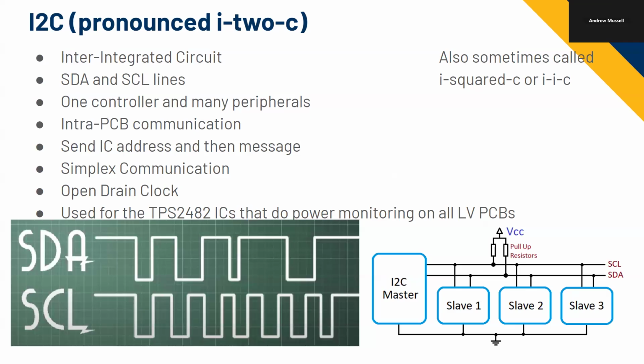So if we were to double the speed, it's 1/2 CV squared times frequency, so it'd be twice as much. But if we could have a lower logic level, voltage is squared. So if you halve the voltage of your logic level, you could actually quarter the amount of power you're consuming. Or also if you halved your capacitance, you could halve the amount of power that you're consuming. Just use a small capacitance, and you don't use as much power.